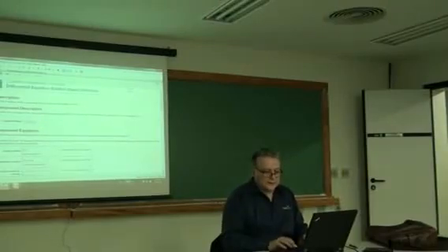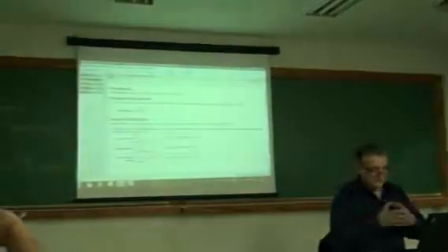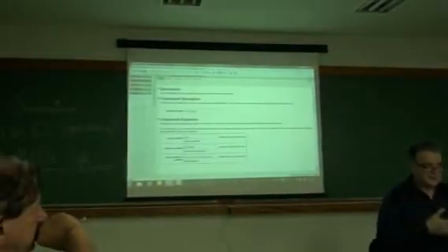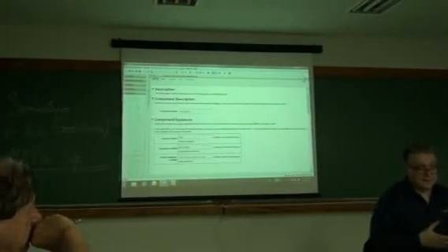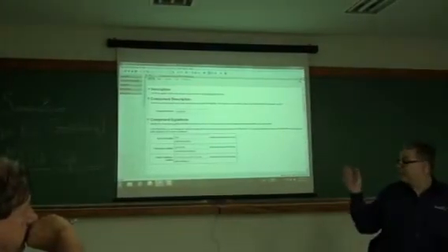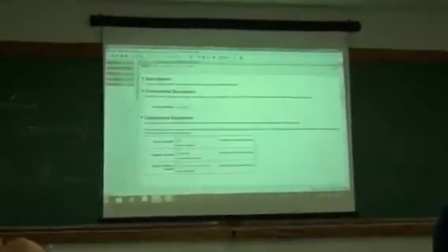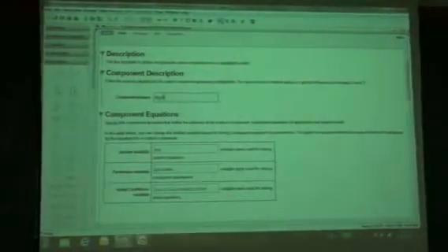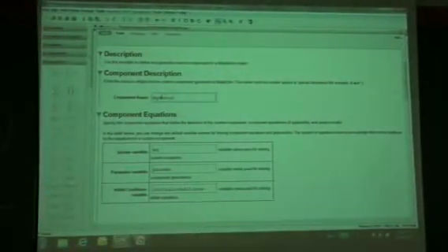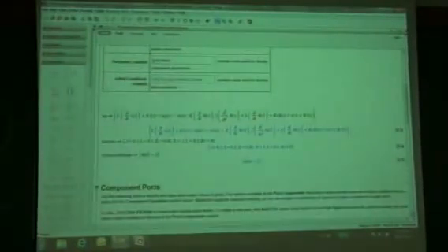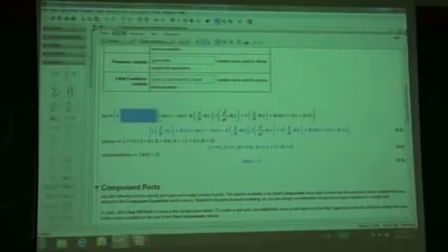So what I'm going to do here is talk about, if you have a system that is mathematically defined and you want to implement it in MapleSim, then you can use this custom components template. This particular one, I'm just going to use it to create an electric motor. I apologize for my engineering examples. And here you simply type in the equations. We have two differential equations that define the behaviors of the system. You just type them in.